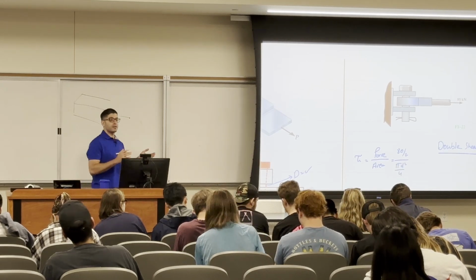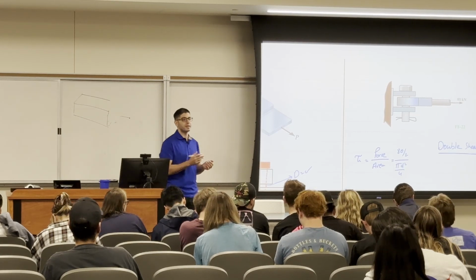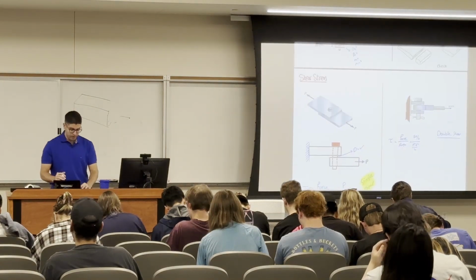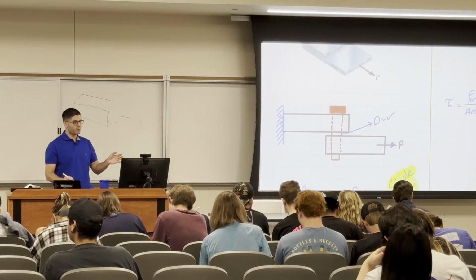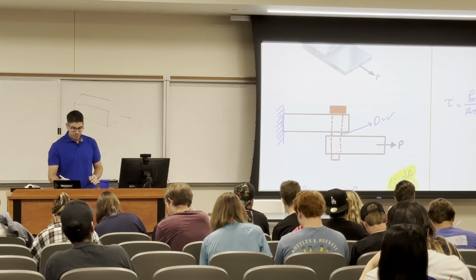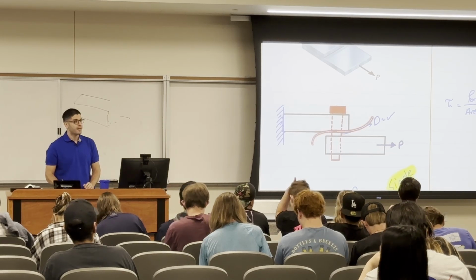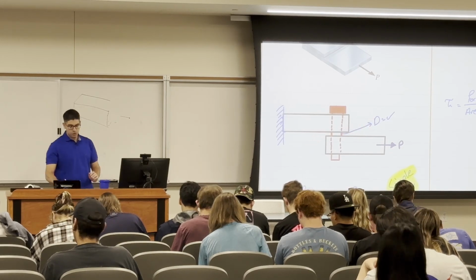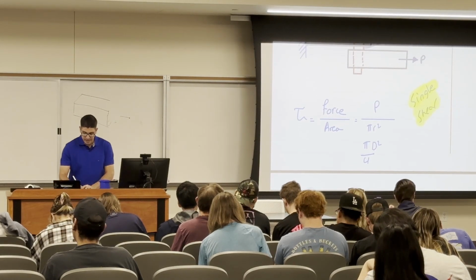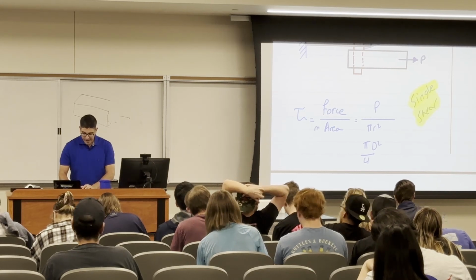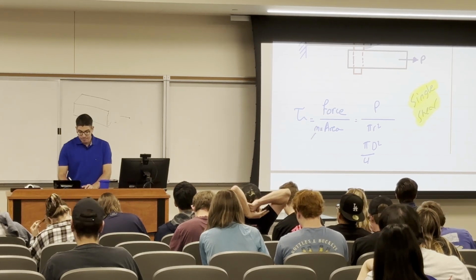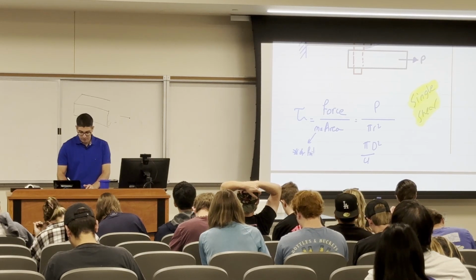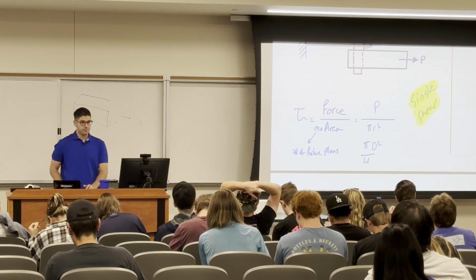This is one way to look at single shear or double shear. The other way is how many planes of failure are going to happen. So here, for example, you all saw from the video that I have one plane of failure, which is where the pin is going to break here. There is no other chance, right? So the equation, we can modify it by multiplying m times area. And m here is the number of failure planes.